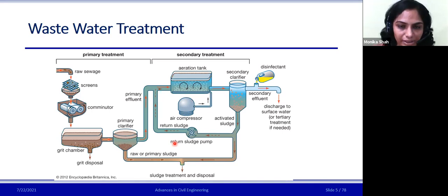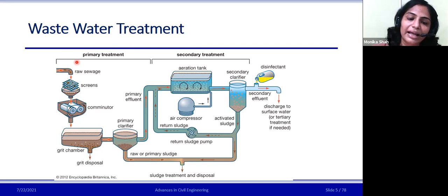Even if we talk about industrial wastewater treatment, the quality of wastewater changes with each and every industry. If you change the manufacturing process, or change some raw material in the process, each and every time we find that the quality of the wastewater changes. So generally, we first apply the primary treatment to that water. The primary treatment is going to remove the visible particles of larger size.